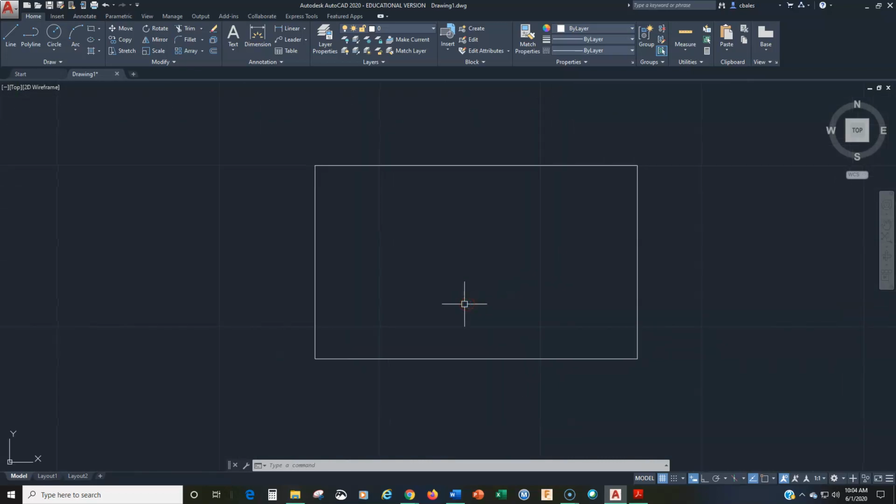And I said that I normally would not start with the rectangle command, and why not? Well, if I click on the rectangle here, notice that it's all joined together. So a rectangle is, there's other objects in AutoCAD that are like this. Polygons are like this. Some of the other features. All of the line objects are stuck together, so it's a single object. And the problem that occurs with that is that we can't treat the lines individually, all right, which is what we want to do in this drawing.